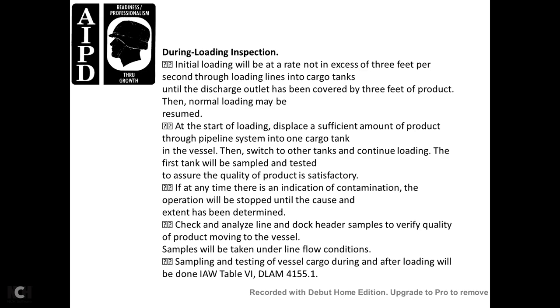Then continue loading. The first tank will be sampled and tested to ensure the product quality is satisfactory. If at any time there is an indication of contamination, operation will be stopped until the cause is determined. Check the analysis and dock header samples to verify the quality of the product. Samples will be taken during and after loading of the vessel, in accordance with table 6, DLAM